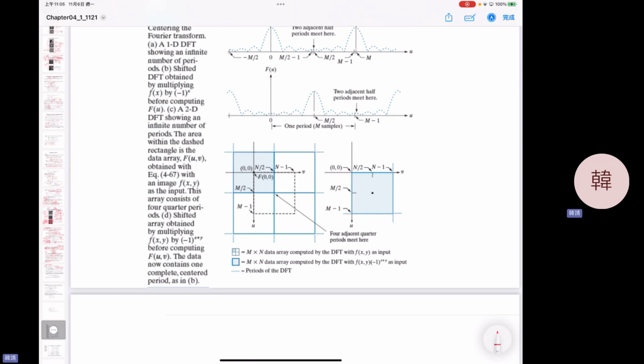And multiplication, okay. Because of the symmetric property between the time domain, spatial domain, and the Fourier domain, when you multiply in the spatial domain or time domain, it actually results in a convolution relationship in the Fourier domain. So if you do multiplication like your sampling process, where H is the sampling function, you are multiplying, so the result will be convolution.